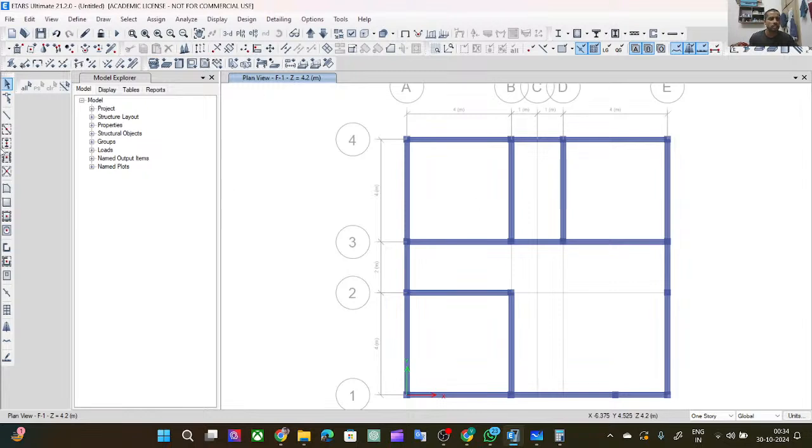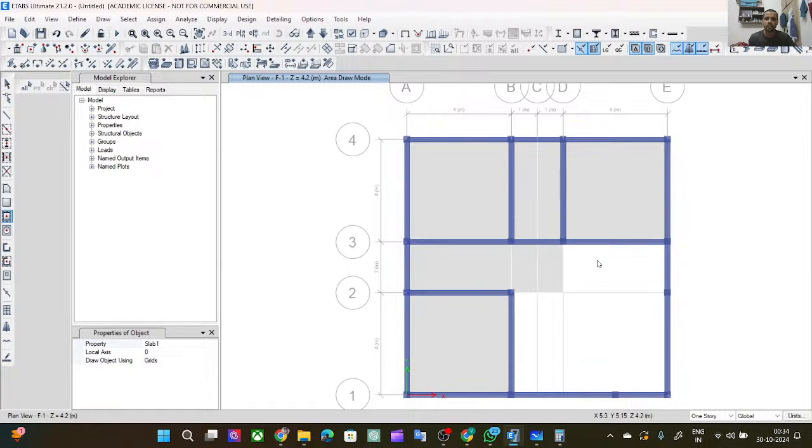Now I will design the slab. Go to quick draw slab, select slab 1, then click 1 and then click 2 and then click 3. But it is one full slab, and it is a two slab, fully two slab. We have two options: I can make all slabs separately and merge them. So I will merge, it is easy for me. I will make all slabs.